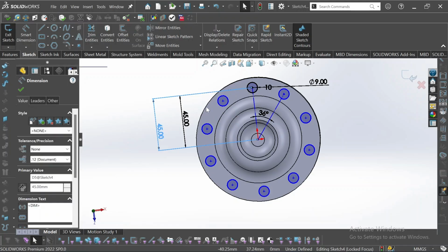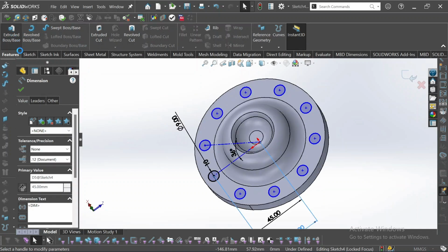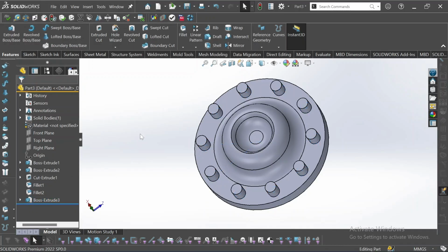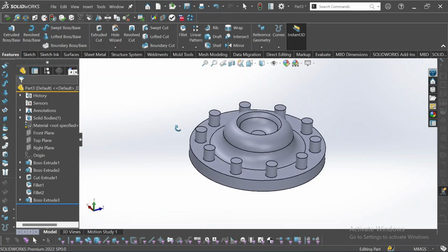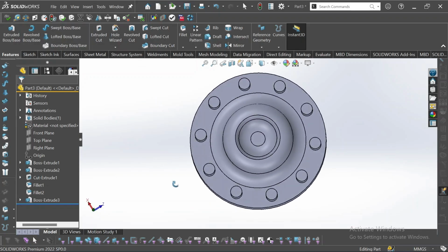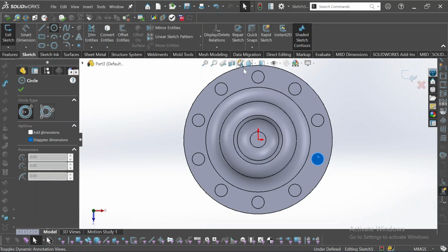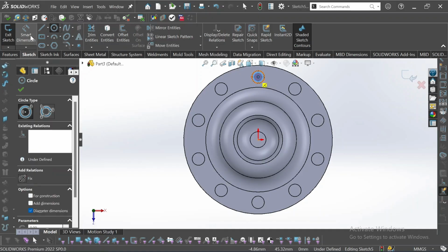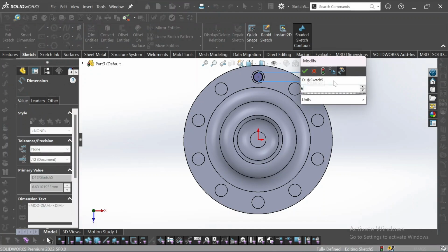So we've done this. We can now extrude this shape the way it is. Extrude. Okay. See? You could do something like this. Very, very simple. You can also, for features, let's say we want to create a hole here. Now we create a hole like this, we give it a smart dimension of 6. 6 is fine.